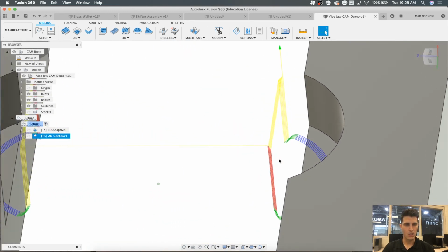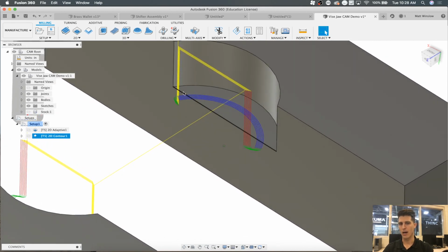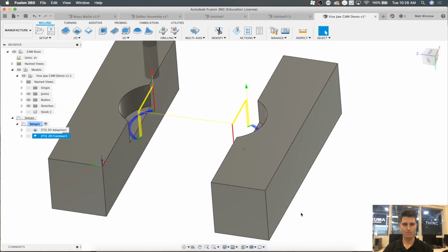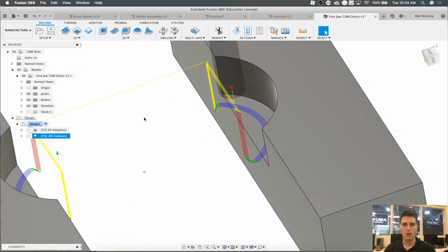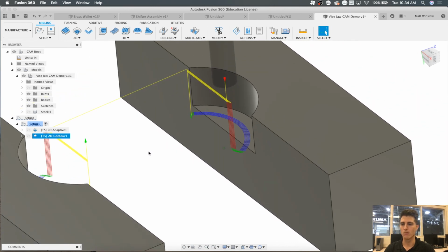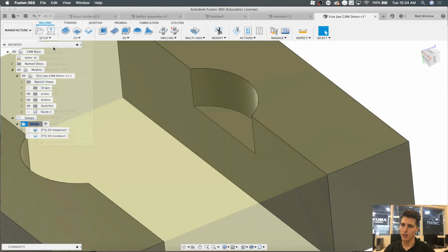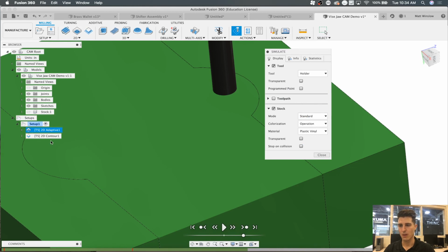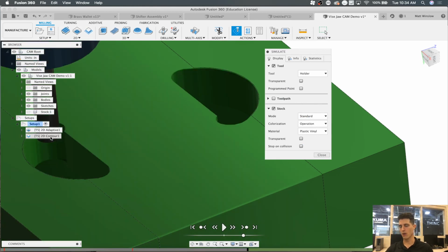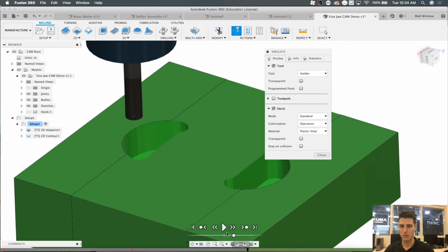And you can see that now we've got our roughing toolpath as well as our finishing toolpath on the wall. We've got a toolpath that looks okay, right? And when we simulate that, I'm concerned that it's not going to cut this portion very well. So instead of simulating it from this contour, I'm going to choose the setup to simulate. And then all I need to do is come down and click contour. And it will do everything above it just like that, which is a very, very cool feature. So very time-saving feature.